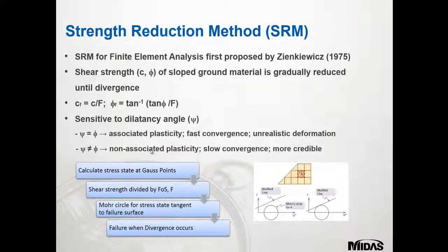So the strength reduction method can model situations including effects of different types of reinforcement, surcharge loads, and groundwater conditions. As it was said in the previous webinar, input of elasticity modulus will also affect how the deformations will occur within the soil, and if reinforcements are present, then their relative ratio would determine the development of strains and displacements as the material shears.